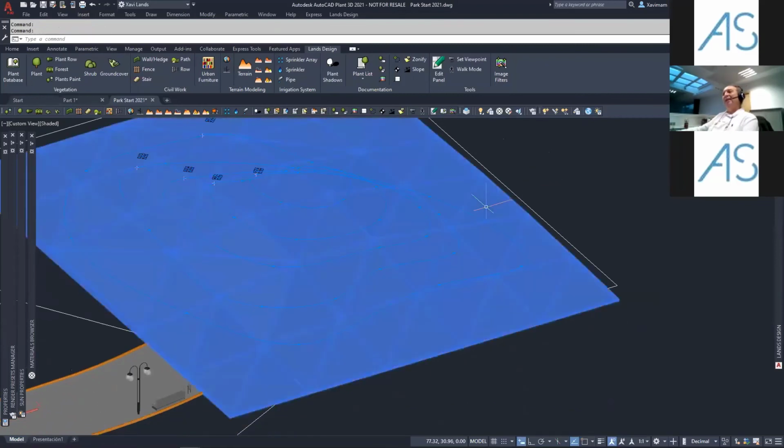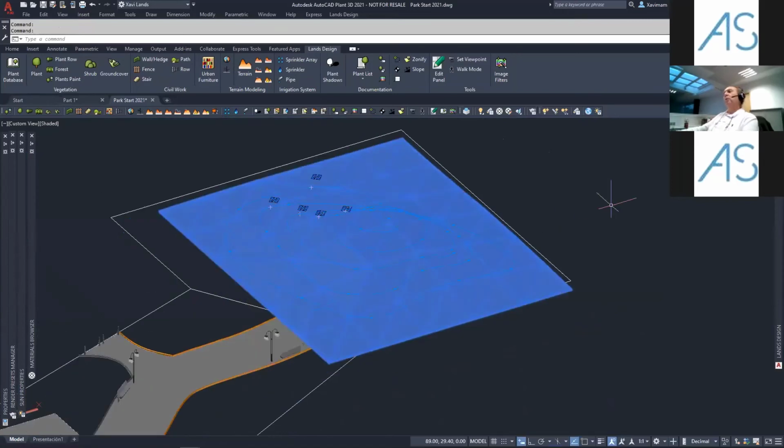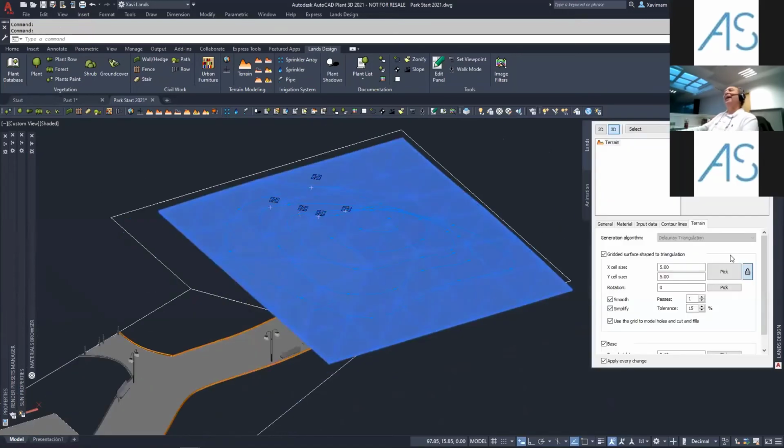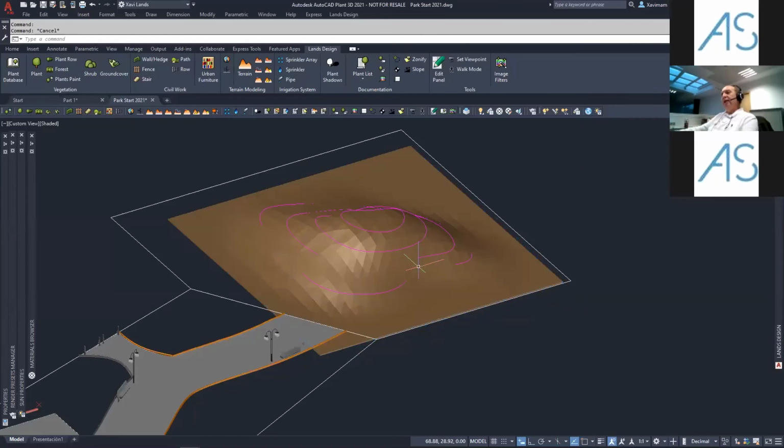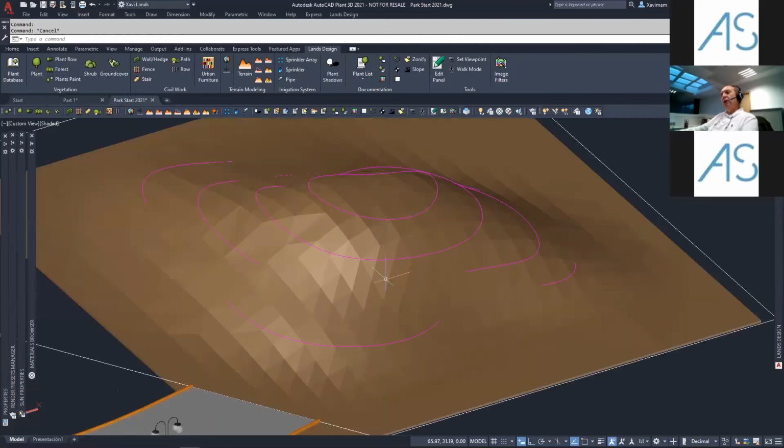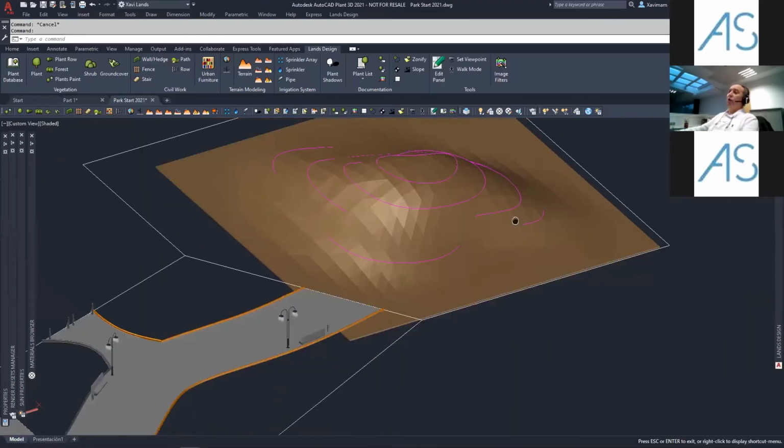Of course, the hill is in a rough view. If I want more quality, again, we have the option to change the value directly from the control panel, the Land Design panel. You can see now that the squares have become smaller, and the quality of the mountain is more accurate, following my contour curves.